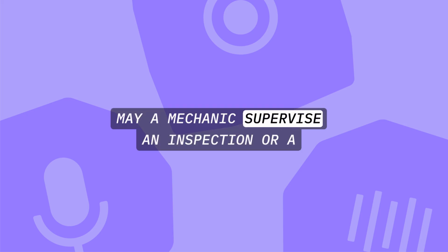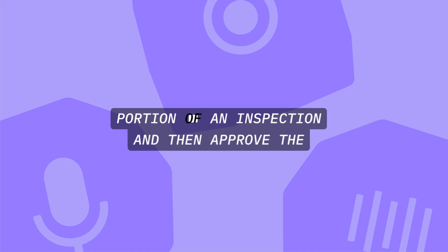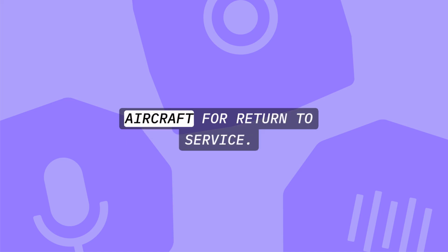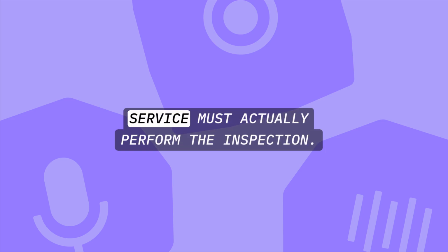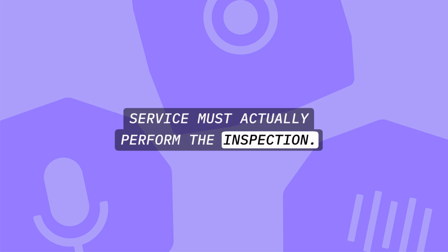May a mechanic supervise an inspection or a portion of an inspection and then approve the aircraft for return to service? No. The mechanic approving the aircraft for return to service must actually perform the inspection.